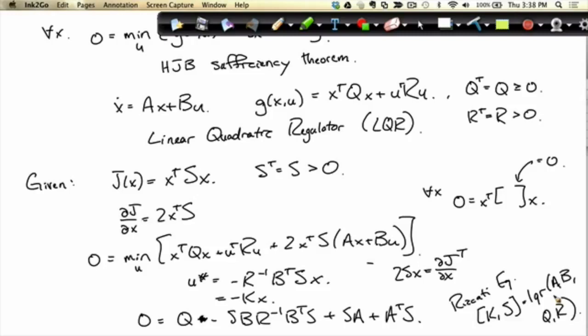Okay, so in practice if we can find the linearization of a system, we can get back a linear feedback controller and the cost-to-go function, and we've done continuous dynamic programming exactly, and it'll be good for the big region of state space that we care about, but not the whole system, right?